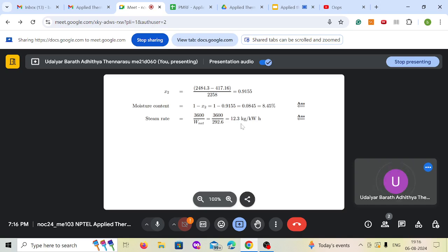A less efficient turbine and pump is creating a higher steam requirement, or mass flow rate, to produce the same amount of work. So you need more steam, so that is increasing your capacity.